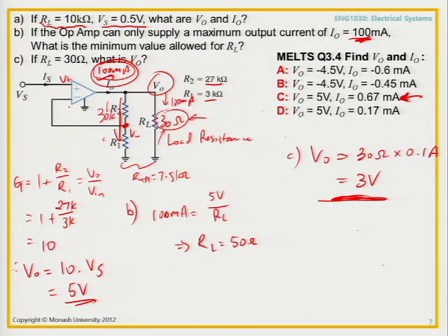You plug it in and your headphone has an 8 ohm load on it, say. Then, let's say if this were 8 ohms, the maximum voltage out would only be something like 0.8 volts, which is totally different from how you designed it, where you designed it to give us a gain of 10 and you expected 5 volts on the output.